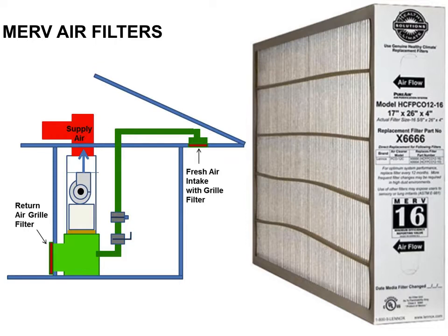That means that we have to push air through a thicker filter, which means you're going to have a little bit more resistance, which means that you need more powerful fans that can often require more energy to be used. So there can be an energy trade-off, just so you know. For LEED, we require or we recommend about a MERV 13 filter. So again, the higher the MERV rating, the thicker the filter.